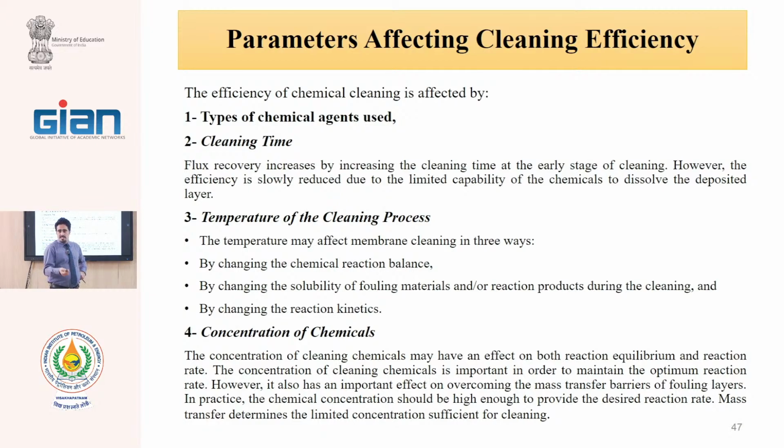We can increase the temperature of the cleaning agent and increase the reaction velocity. The concentration of the cleaning agent is important. In some cases, we use the acid with pH 1, sometimes pH 2. And with change of the pH, that means the concentration changes. The concentration of EDTA is important.